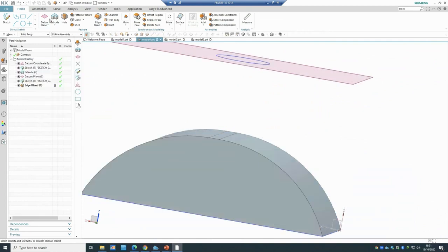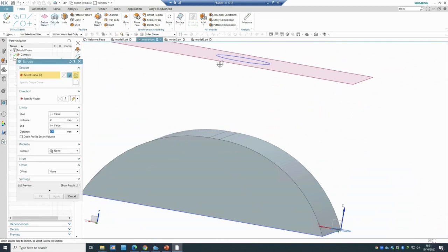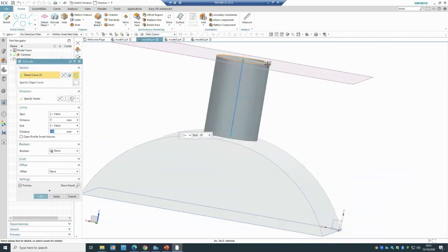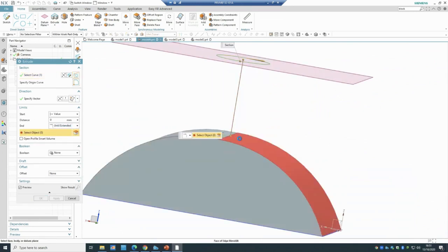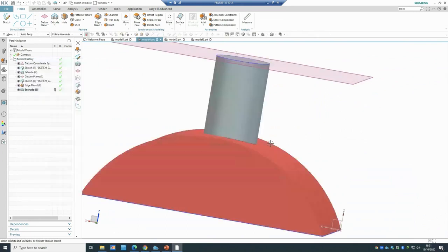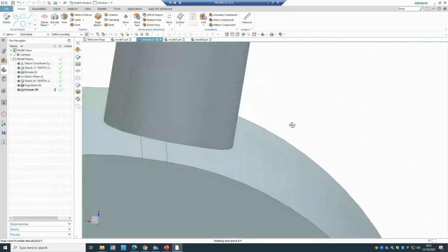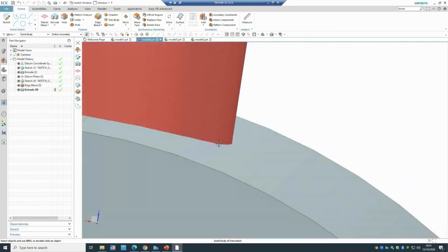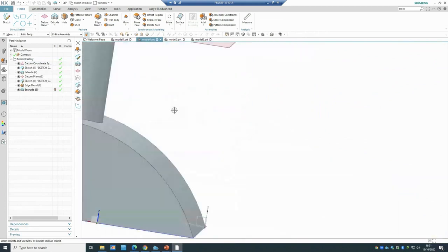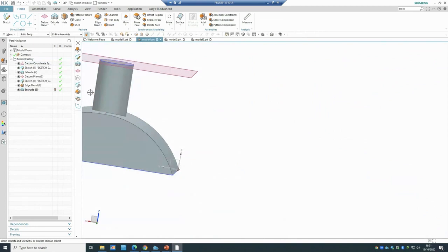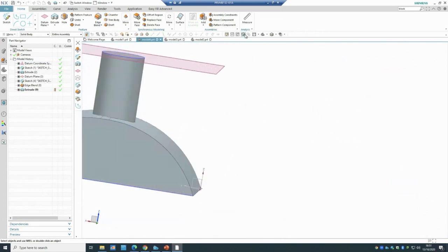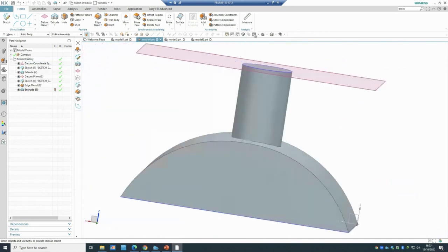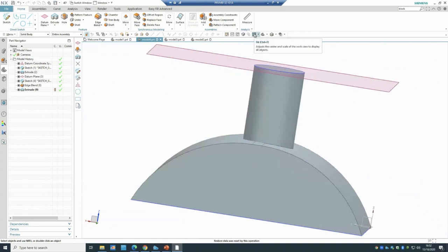And now I do extrude. So the steps are really important. What you will be able to do is until extended. Or just pick this one, click OK. You see that it is actually extended, so you have the curve on the top. So this is when you will have the until extended. Whenever we have a curved area, you want to extrude and completely cover that one.